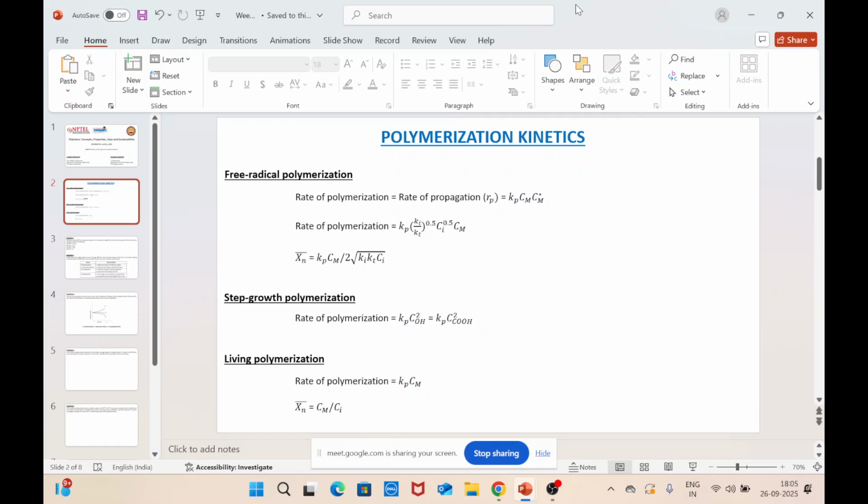Again, at high temperature it's going to be easier to fill the cavity, but if the temperature is not sufficiently high, then the ability to flow is going to be restricted, and because of this, a high viscosity is exhibited by the polymer melt, so it becomes far more difficult to fill the cavity compared to the polymer melt which is at an elevated temperature.